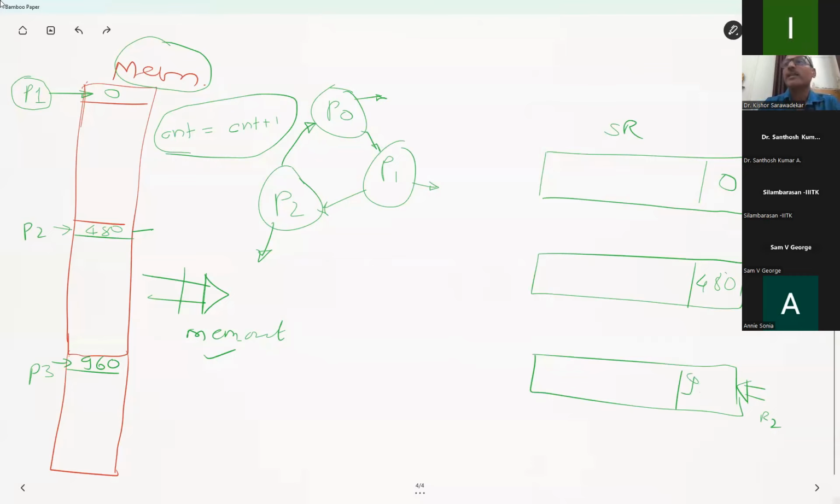But now this is hypothetical. 3 shift registers are there, shift register 0, SR1, SR2, corresponding to the rows. But there is only one line, and this line should reach here. How do we do that now? There must be something here. That is what a basic digital design course will tell you. So we need to have a decoder here, a demux, not decoder, demux.